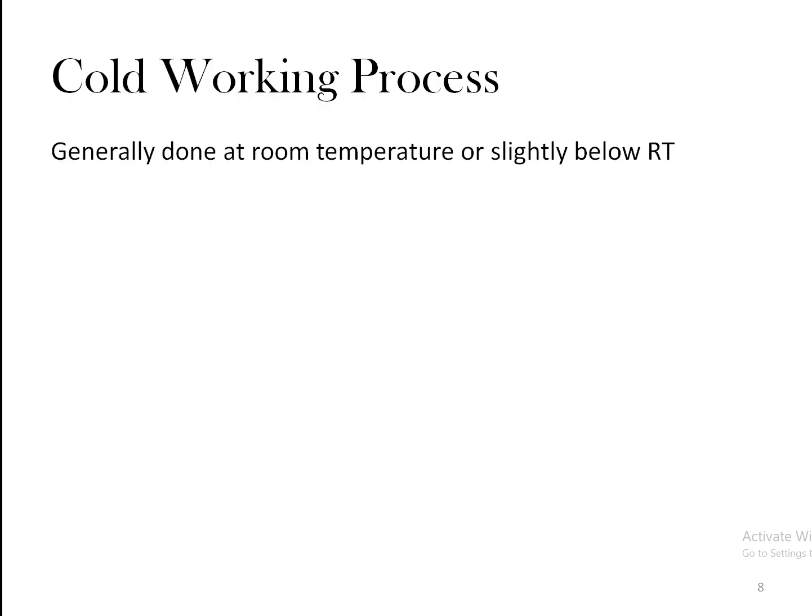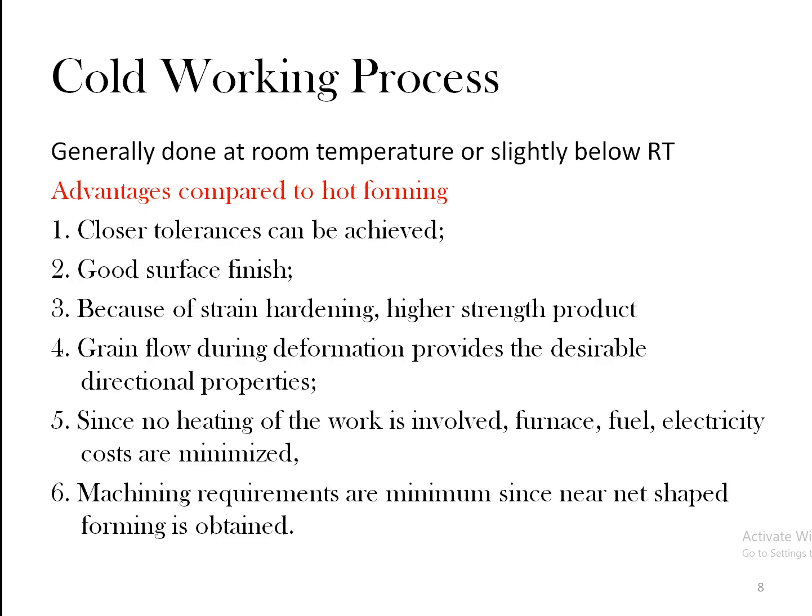One is cold working, where the complete process is done at room temperature or slightly below room temperature. It has different advantages compared to the hot forming process: you'll get a good surface finish, the tolerance will be good, and because of strain hardening, you'll get a higher strength product, etc. All these things are the basic advantages of the cold working process.